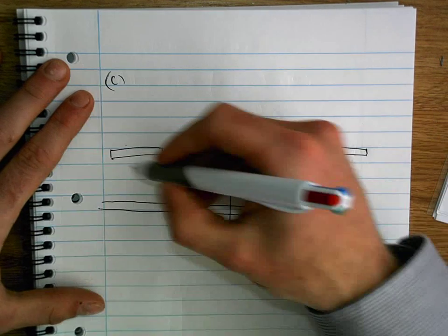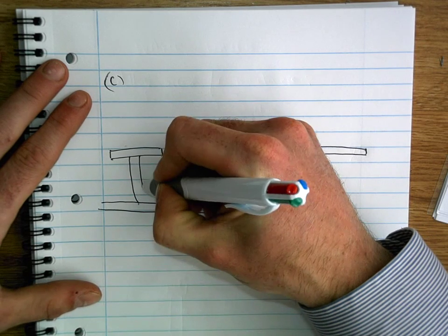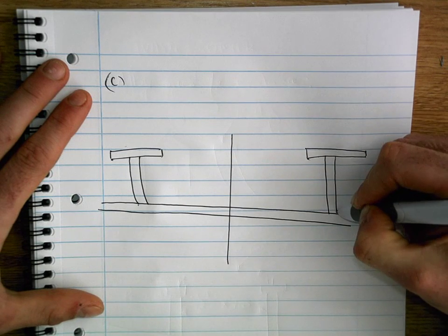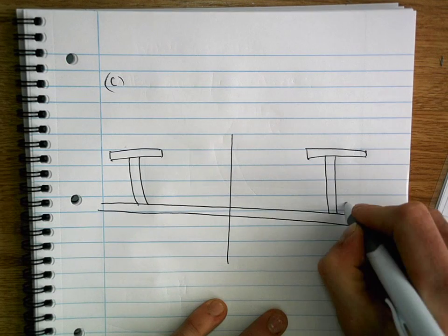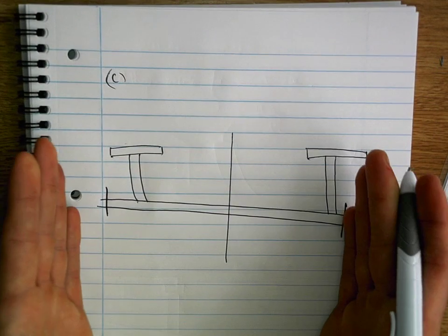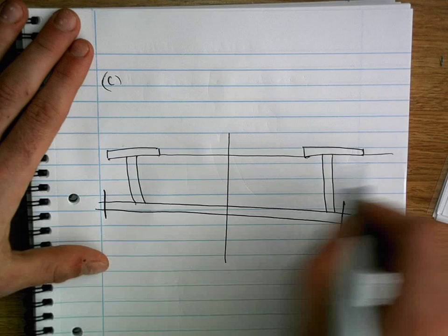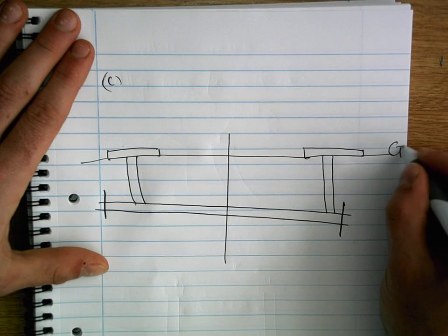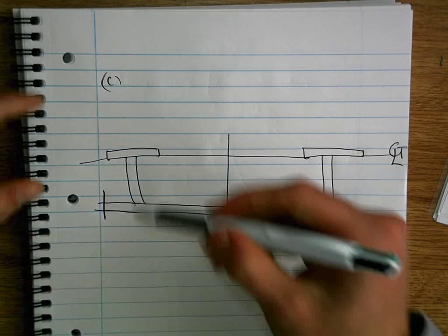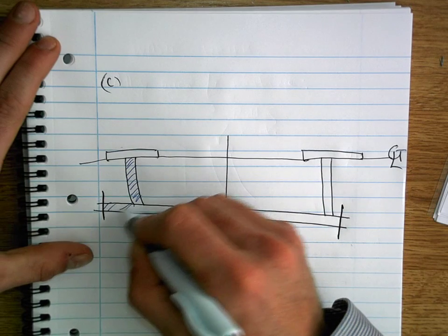What we're going to do is we're going to put down a down pipe which would fit into a connection here. We're going to do the same on this end, and you can actually block off those pipes left and right. So now you're just testing this area. Remember, this is your ground level here. This is all underground. Now what we will do is we will pour water in from one end. Obviously the whole pipe work will fill up, so I'll just shade that in blue.